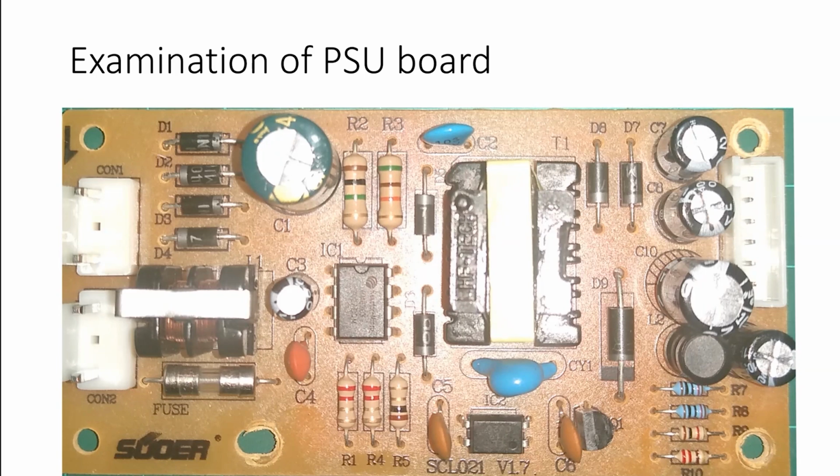And then you've got the common mode choke or inrush choke. Now, we talked about these earlier on when I did the circuit protection presentation a few months ago. Common mode chokes stop inrush current and stop noise from the mains getting into the power supply, or more importantly, from the power supply getting out to the mains.